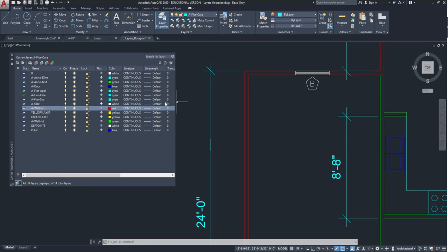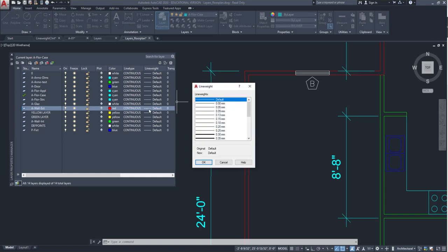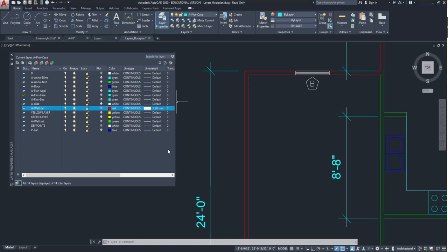I know it's a lot. If you haven't done it before, it doesn't make a whole lot of sense. But basically, what this will allow you to do, if I change this, right, you see how this has all those pen weights defined, okay? So I could take this and say, well, red means 1.2 millimeters, okay. And by changing this right here, I built in the thickness of that line weight, all right?